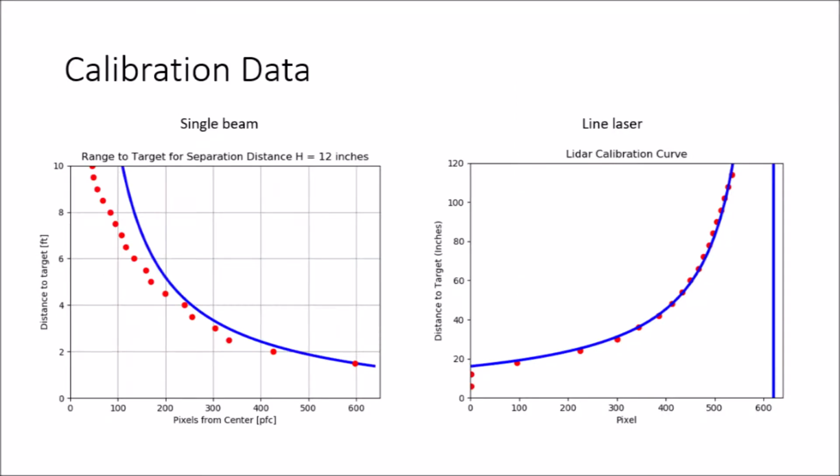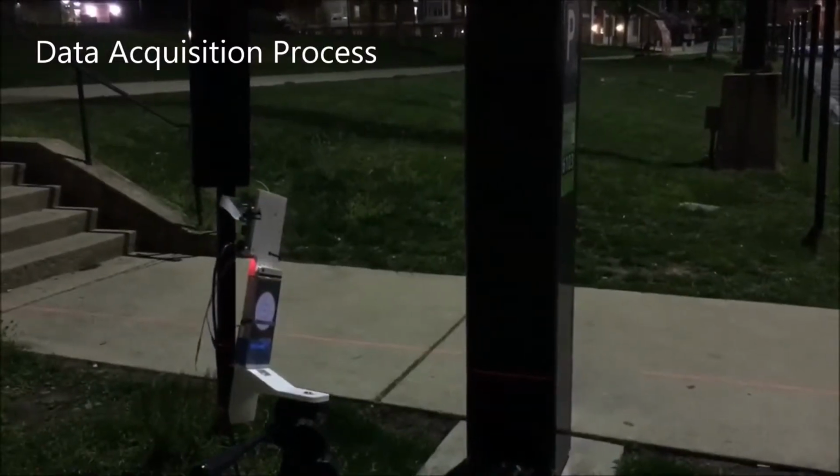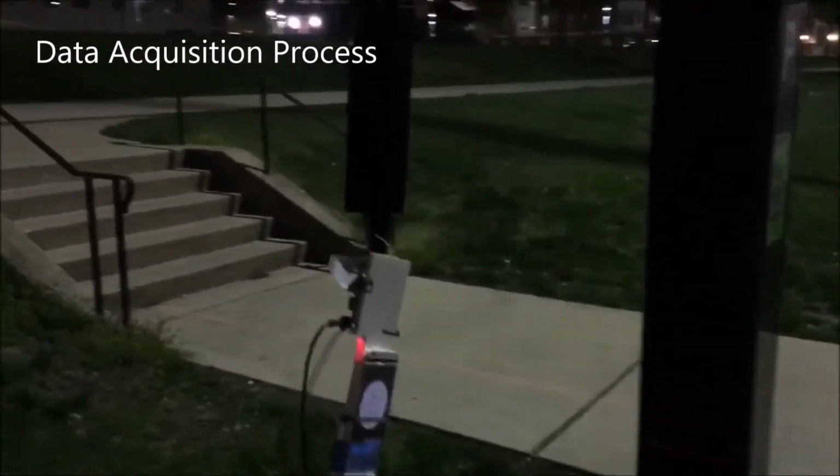Here is the calibration data for a single beam laser and the line laser. The blue line represents the theoretical data and the red line represents the taken data. These calibrations were done for a separation distance of 12 inches, and within the Python script, the RO and RPC values were changed in order to get the calibration data to line up as closely as possible to the theoretical line. Here's my data acquisition setup.